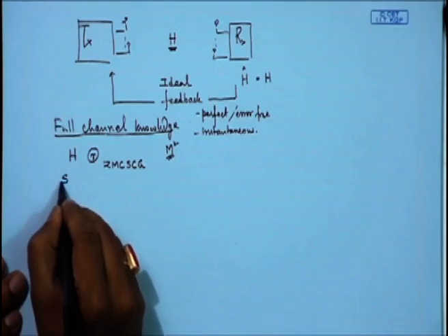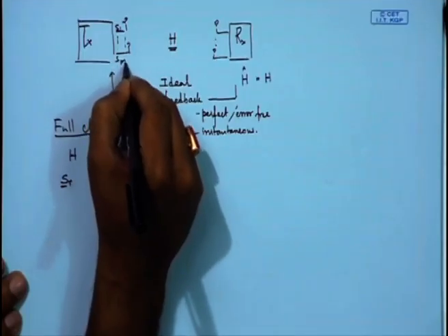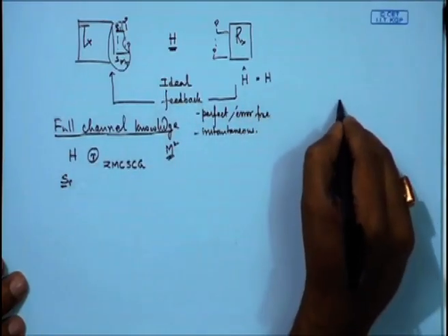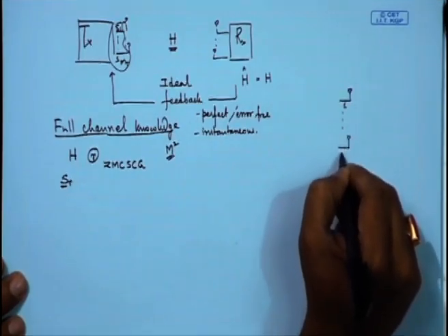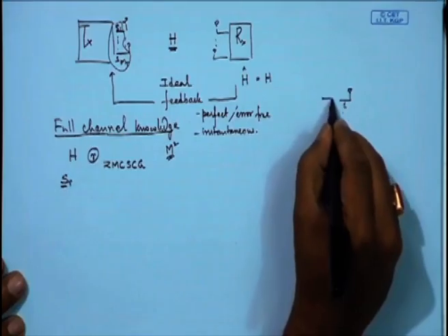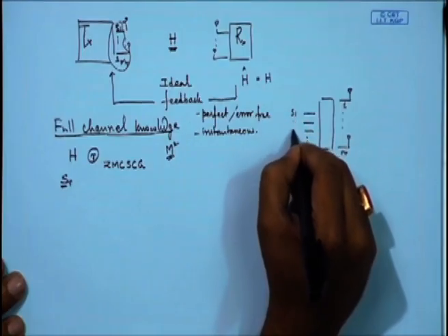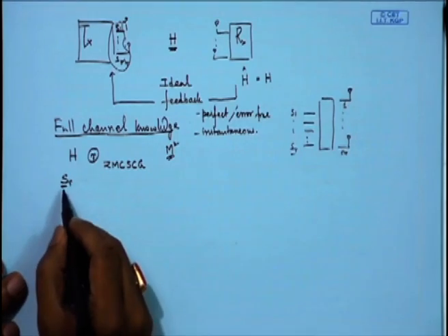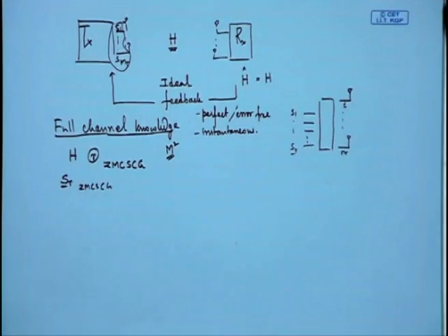And this vector S R is basically S1 up to S R. We usually have S M T, but now we are saying that no, this is not what we are doing. Instead, if I need to draw it again, channel number 1 up to channel number M T, right? There is some processing unit before this, and here there is S1 up to S R, the number of symbols which are being sent from the transmitter. So S R is the vector which will be used. Again, this is zero mean, circular symmetric, complex Gaussian. That is what we will assume.